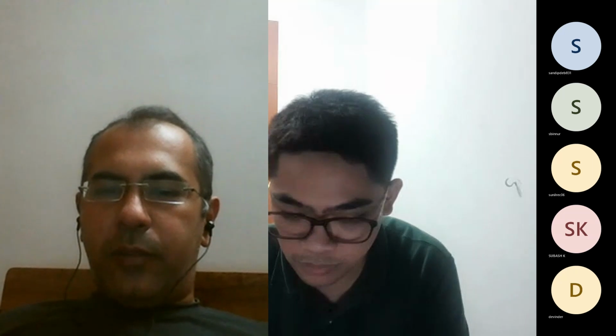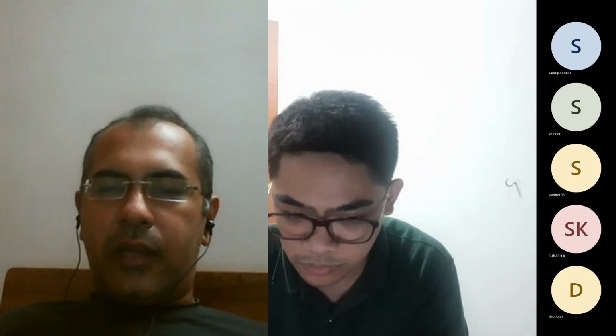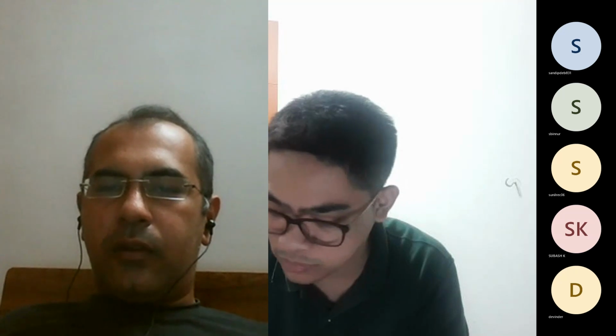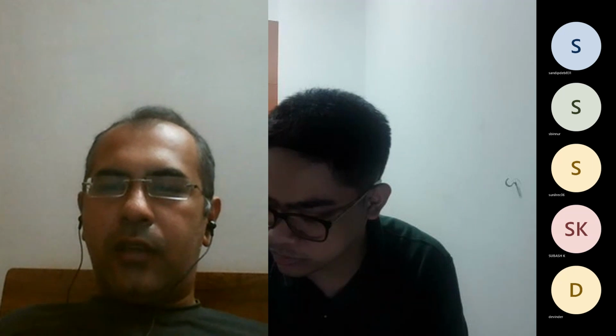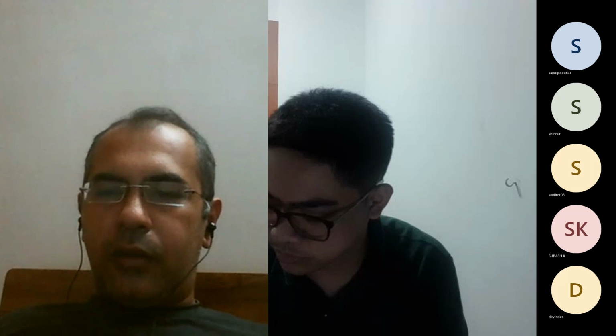Okay, so try to make an Excel for your own self, because that is the manual analysis, and then we can compare with ETABS: whatever you are doing in Excel, the same or nearby should be in ETABS. Otherwise, the ETABS is wrong. Okay, so that is how we are doing it.